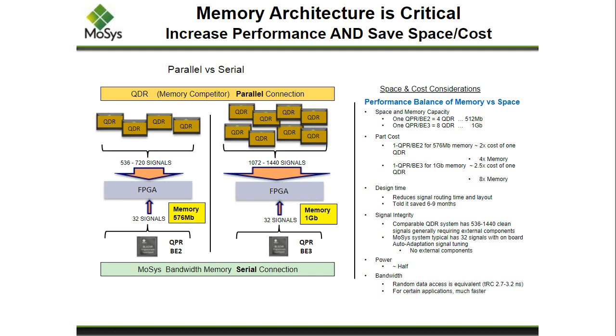And we also started looking at the routing on a PCB. If you take 4 QDR devices, there's literally hundreds of pins you have to route, and they have very strict layout requirements. Whereas in the bandwidth engine devices, because we use SerDes, you have that flexibility of a little longer routes and not being so intolerant of matching things.